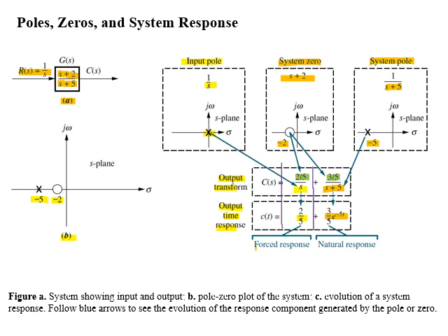In second term, we were having 3/5 multiplied by 1/(s+5). Now if we take inverse Laplace of 1/(s+5), we get e^(-5t). So this portion e^(-5t) is due to system response or pole of the system, and this will be our natural response of the system.